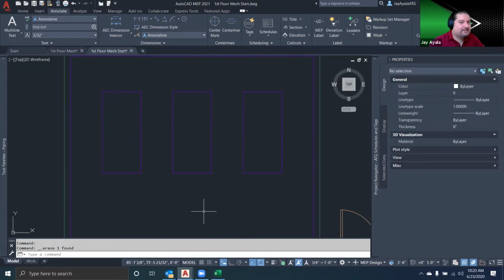This is important because there have been so many times on projects I've worked on in the past, where a document has gone out and somebody reviewing the document has said, hey, I see that you have a tag here for a diffuser. Where is the diffuser? I don't see where the diffuser is. It's because, again, these things are disconnected. In the example where I had a block and an attributed block to be the tag for that block, those things are not anchored. So if I delete the pump, there's a potential where I could leave that tag behind. With this system, it's all inclusive.